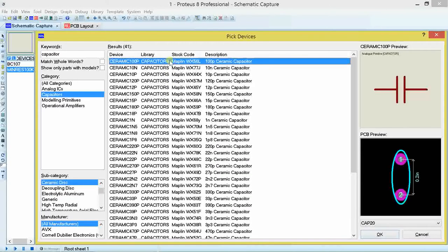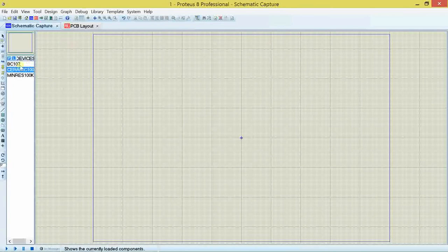Use any one of them. Double click on it and it will be added here, then close it and select the component to add. The cursor is like this. Press once, choose where to place the component, and click again. Then select the resistor. To rotate, press plus, and place the component where you like.